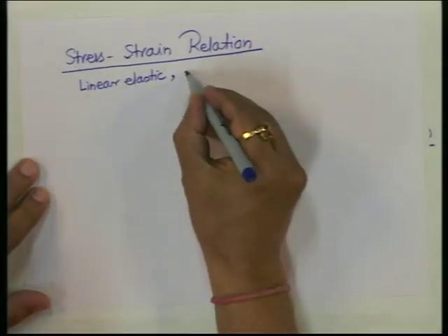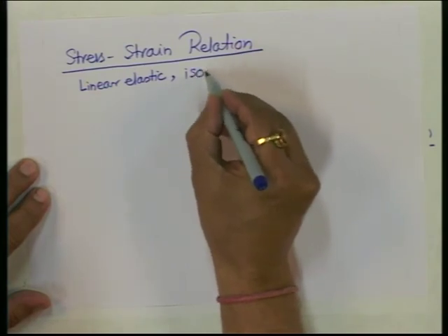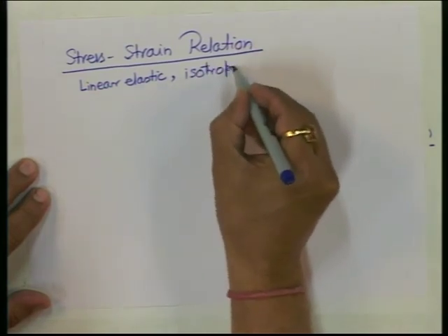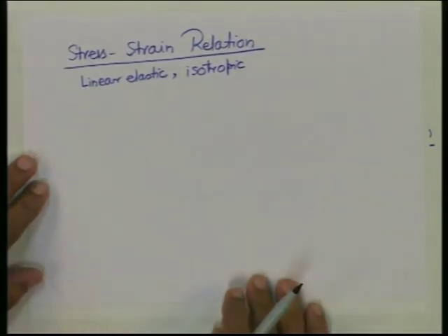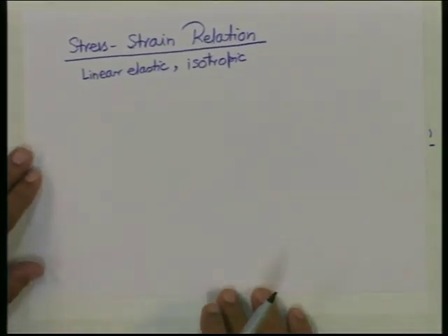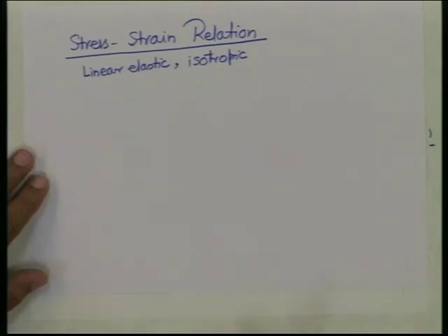And isotropic. Somebody recently, I was in an interview, and I asked how do you define an isotropic body or isotropic material? Quite a middle level person, he said E, nu and G. For 5 minutes I said there is no relationship among these three. You need three constants to define isotropic material? Yes sir, we need three.